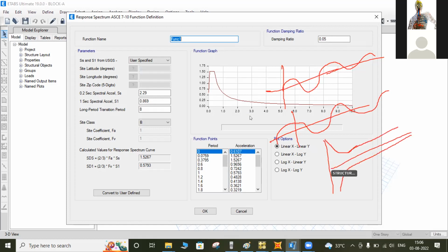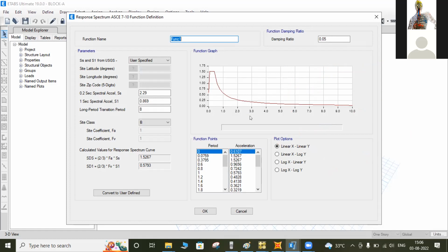So we have two methods for seismic analysis. We have this RSM, and we have what kind of analysis, Karim? That is the time history method. In the time history method, we are taking data from our previous records, and here we are applying the code. We have the earthquake analysis recommendation from the IS code also. Which IS code, Karim, is applicable here? IS 1893. We have to use it for performing the seismic analysis, sir. Yes, IS 1893. So this is the code that we are going to use in this one.